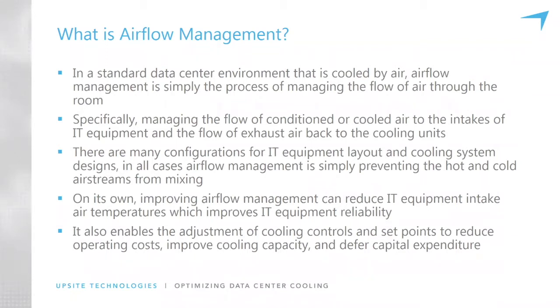The benefits, as I mentioned, of improving airflow management, they can reduce IT equipment intake air temperatures. Getting rid of hot spots is one of the first and most important things to achieve. You know, every data center in the world can be classified into one of two conditions: data centers that are providing appropriate intake air temperatures and those that are not. So if a data center is not providing appropriate intake air temperatures, then that needs to be fixed right away. But if all the intake temperatures are appropriate, no hot spots, no cold spots, then the question is, can it be more efficient? Can airflow management be improved so that cooling optimization can take place and operating costs can be reduced?